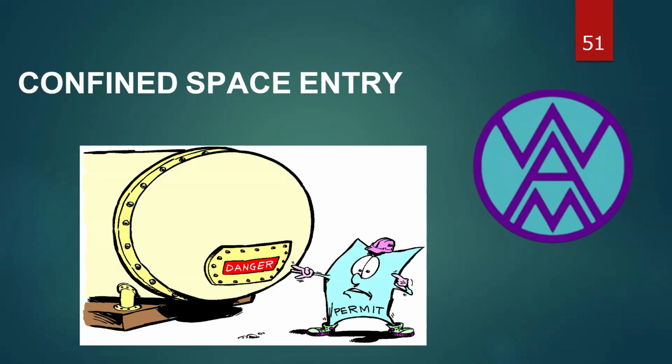What does confined mean? It means a limited area. For example, one of you gave me excavation. If it's more than 5 feet, then it can be a confined space. If there's a limitation of oxygen level, if there are toxic gases, or if a person cannot work there for a long time, that will be a confined space.